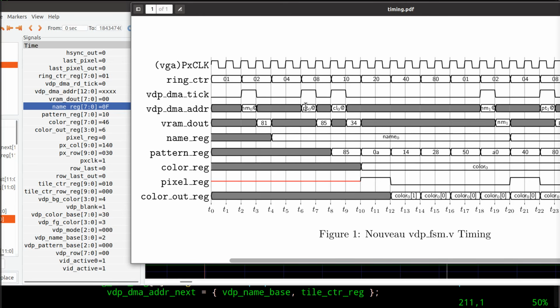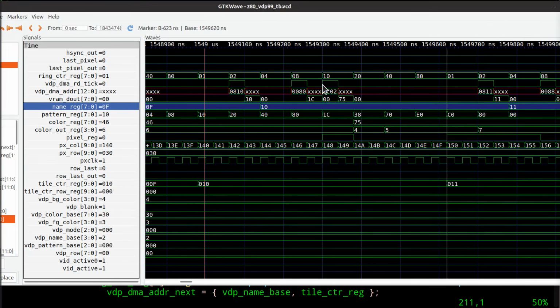So when we get this pattern here, the second time we see the data come from the DRAM out is when we get our pattern and these bits. And hopefully we'll see there's a single bit on in this section here when we fetch that. So here's the first one. The second one comes in. I got a 1C here. Well, that has more than one pixel set. Why would that?